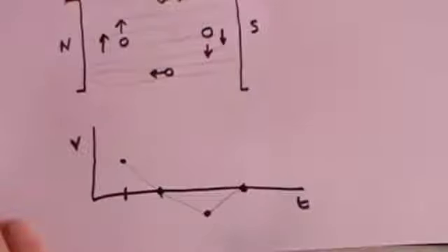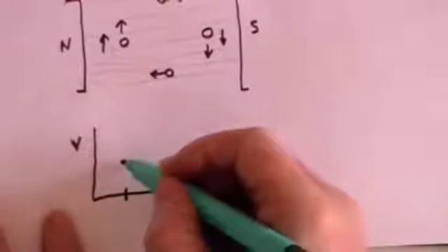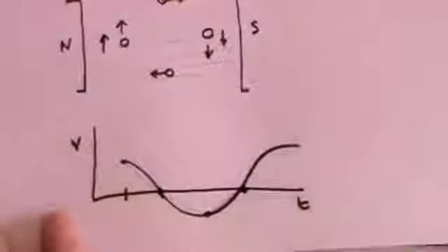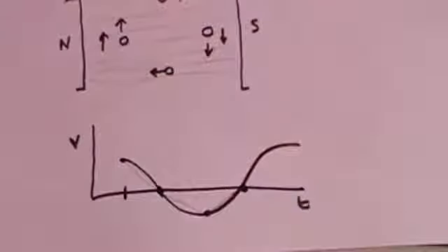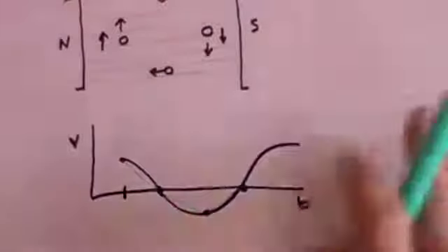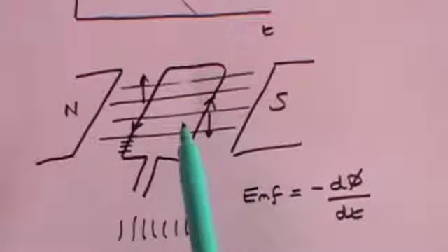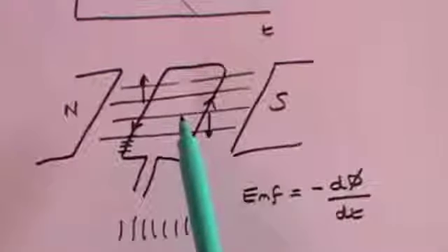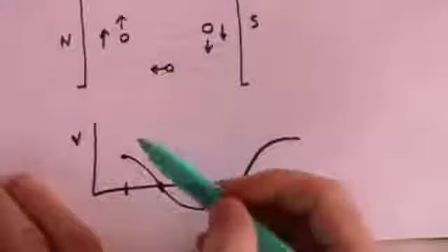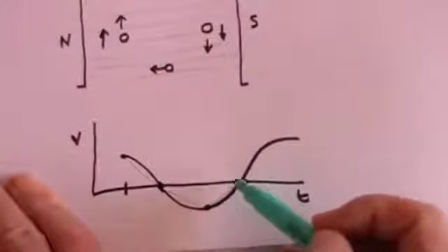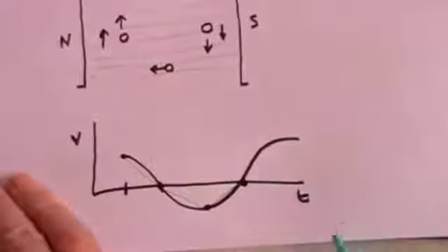In fact, what is happening is the change in the voltage is running according to the sine wave. I'll describe that mathematically in a moment, but what it actually looks like is this. It's a sine wave. And so consequently, as the wire turns in the magnetic field, it is constantly changing the voltage and the associated current. It starts at a peak voltage, it drops to zero. It goes to the negative peak voltage, it drops to zero. It goes to the positive peak voltage, and so on.